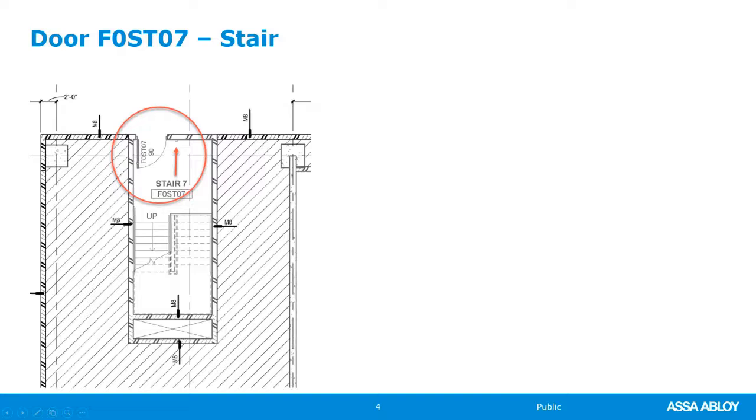And that means that from the stair side, they want a card reader to be able to access the basement level. And whenever we do this, we know that card access on any kind of stair, unless it's at the level of exit discharge leading to the outside, this door has to be fail-safe so that if there is a fire and somebody is trying to exit up and they smell smoke, they can open the door and find another exit stair to get out of the building.